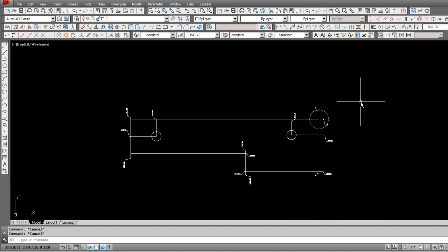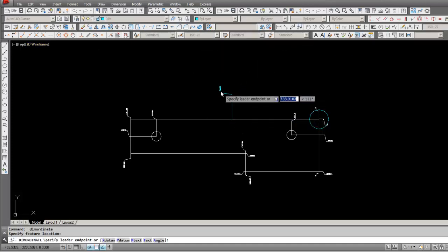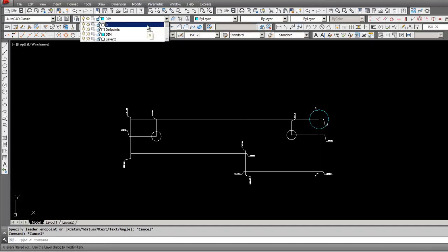Or if you know earlier, you could have changed it in the beginning itself: you select DIM and draw the dimension. Suppose I selected this and draw the dimension, automatically we can draw in the dimension. Since we have not selected earlier, we have forgotten, intentionally I forgot.